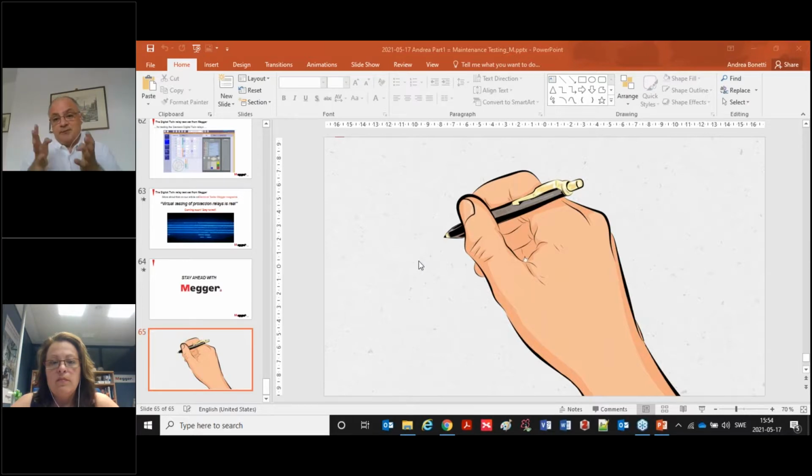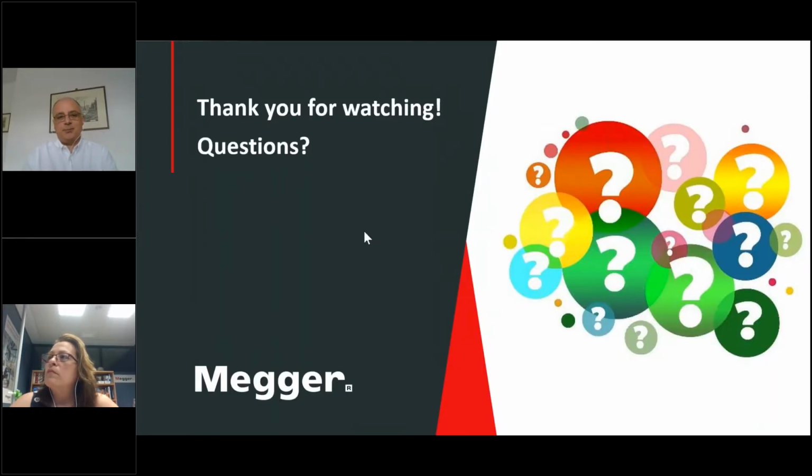Fine, but the digital relay is connected to the breaker with an analog circuit, and connected to the current transformer with an analog circuit. So philosophically speaking, the analog circuit can get broken anytime. The trip circuit can get broken anytime. So this is what is giving you the demand on testing your protection relay.